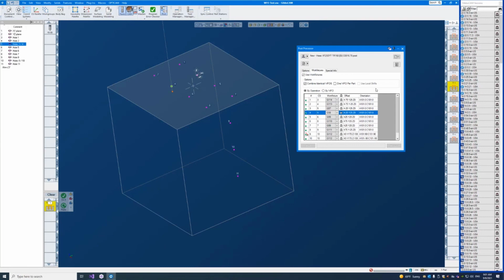I think one of the important things to realize is that part of what we're trying to address is that exact thing that you said, which is you have to know all this before you start. You shouldn't have to know it before you start. You should be able to say, how do I want to machine this part, before you need to determine exactly how that's going to match up to a particular machine. And that is part of what gives you machine independence, being able to run a part on several different machines, which is something that happens in the real world.